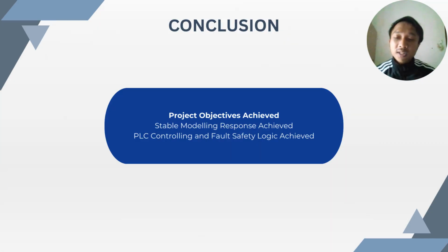To conclude, the project successfully achieves its core objectives by delivering an optimized, practical, and energy-efficient electromechanical VIGV control system for the Siemens SGT-500 gas turbine. By integrating a basic PLC, a 415-volt electric servo motor with a precision gearbox, and a rotary encoder, the design meets the strict response requirement of under 2 seconds under continuous duty. This sustainable engineering solution not only enhances compressor operational stability and power efficiency, but also establishes a reliable safety architecture through hardwired end stop interlocks and real-time sensor fault alarms for long-term industrial impact.